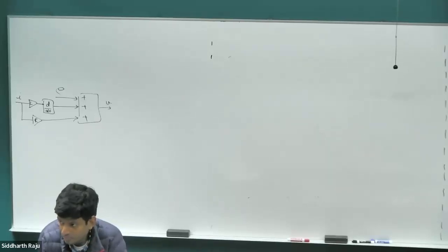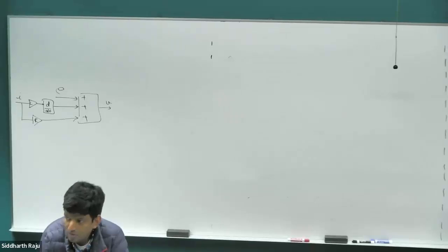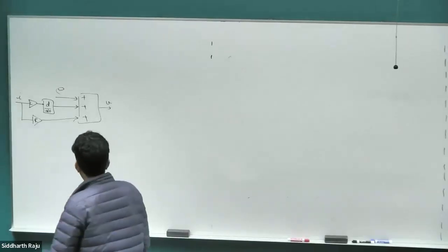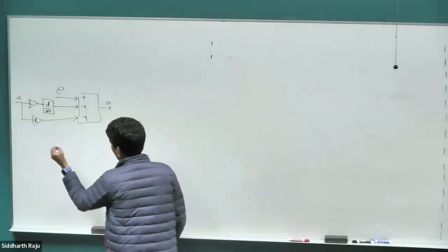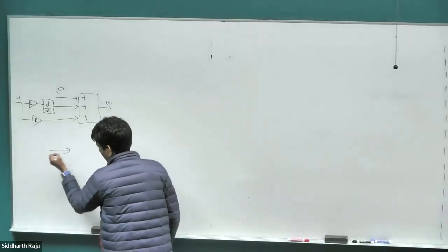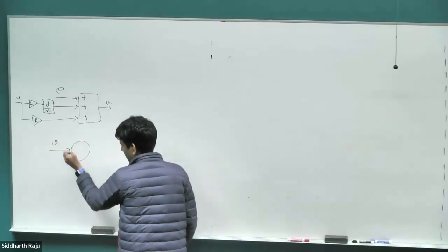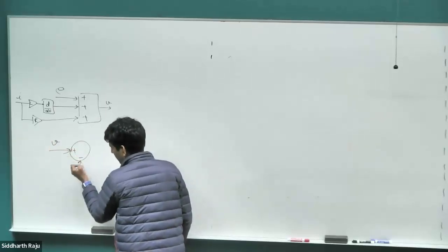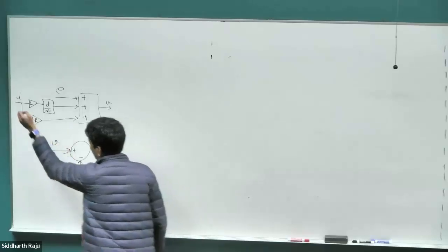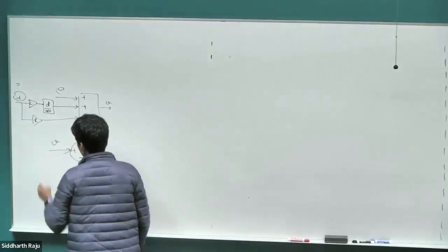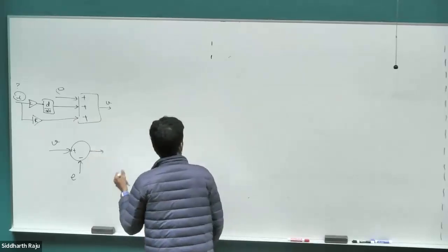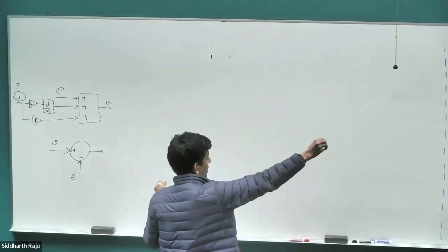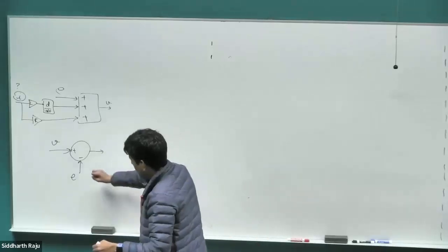You do the inverse process where you subtract off the EMF and you back calculate the current. Perfect. Back calculate. So there are two methods. The answer Ben gave is you have the voltage, subtract out the EMF. We don't know what the EMF is. Here again, we don't know what the current is. The voltage is the only given value. You subtract out the EMF, and whatever remains is L di by dt plus Ra, right? So this is one possible solution.